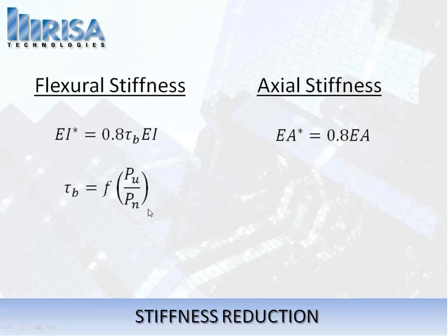Well, here we run into an issue relating to finite element solving of a model. That is, when we have a statically indeterminate system and we solve it using a finite element analysis method, we determine the force in the member based on the stiffness of the member. That's an inherent thing that goes all the way back to even the virtual work stiffness methods that you would do for any sort of indeterminate structure.